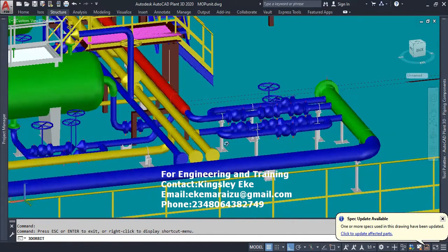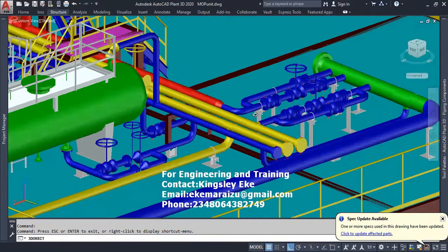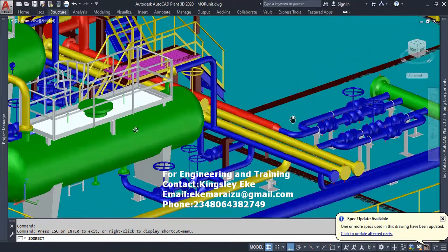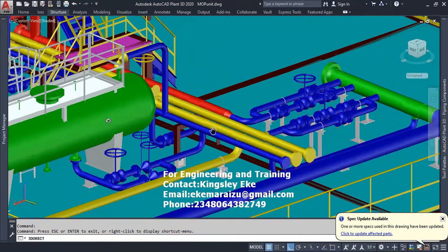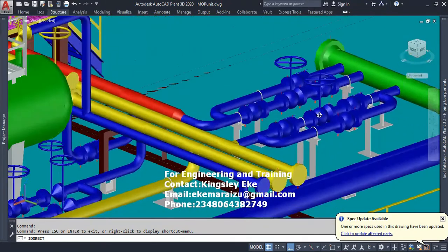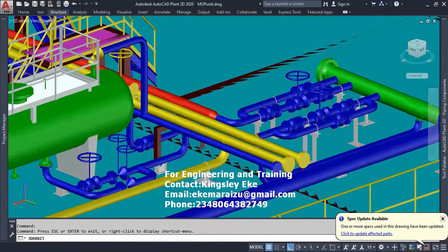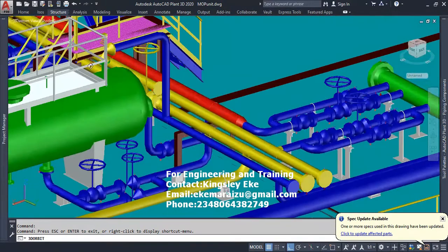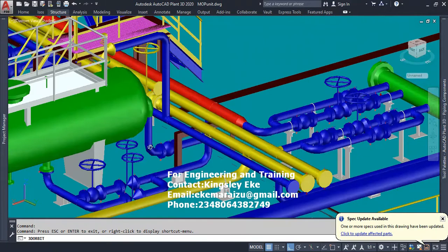Now, there are some critical elements that ensure that the operating pressure of this vessel is maintained. For instance, for the LP separator, we have a pressure control valve. This ensures that the operating pressure of 5 bar is maintained in this LP separator. When there is a process upset, it is relieved on this relief valve and all routed to this header.